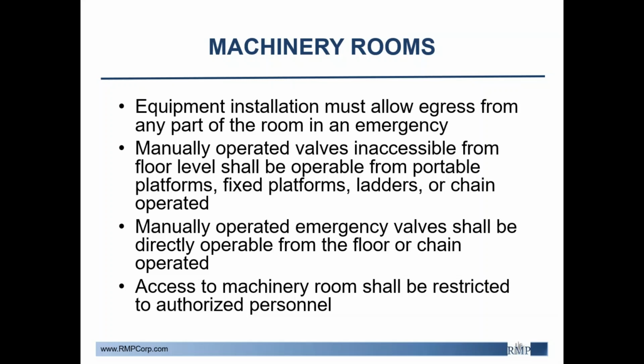Also, access to valves and when they should be accessible in an emergency. You shouldn't have to climb any ladders. You shouldn't have to climb any stairs to access those valves. In a non-emergency, it really doesn't matter as long as they're accessible. So knowing the difference, having those valves accessible, marking those valves.